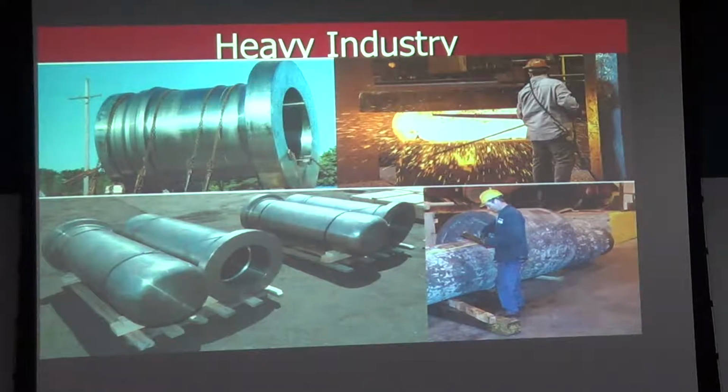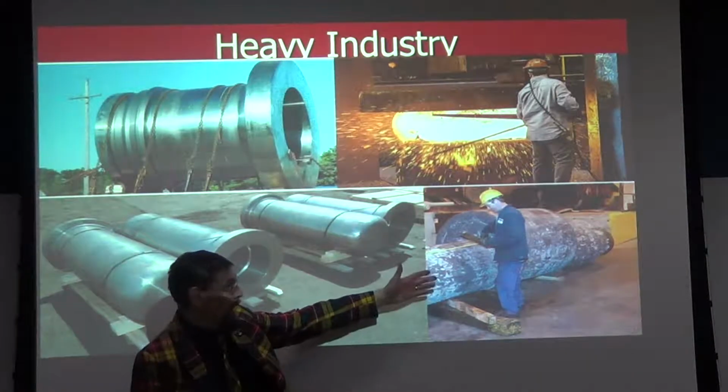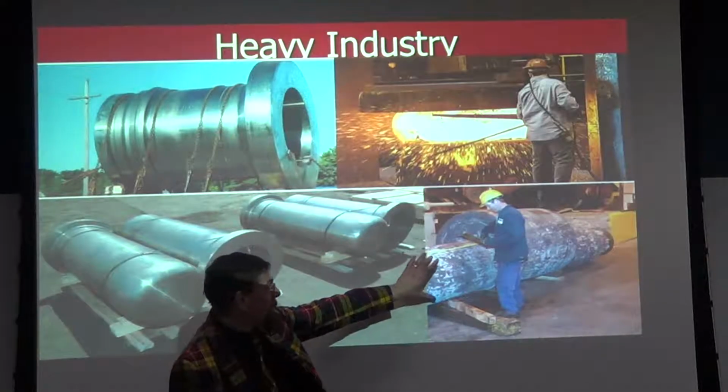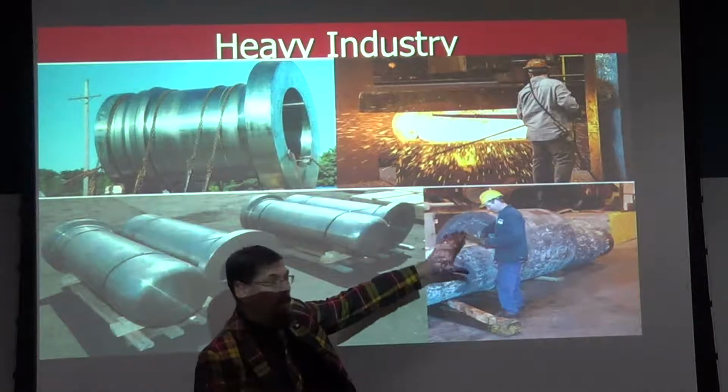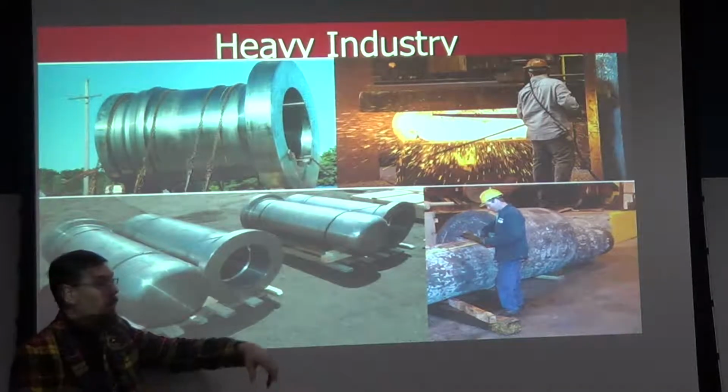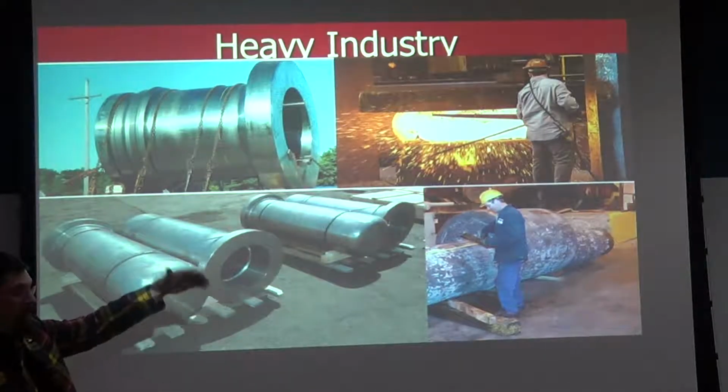This is just a sort of general catch-all category, general heavy industry. What you see over here is what we call an eccentric or crankshaft. So you've got the main shaft here, and you have a much larger diameter here, but the two don't have the same center line. So this would allow you to make something go up and down.